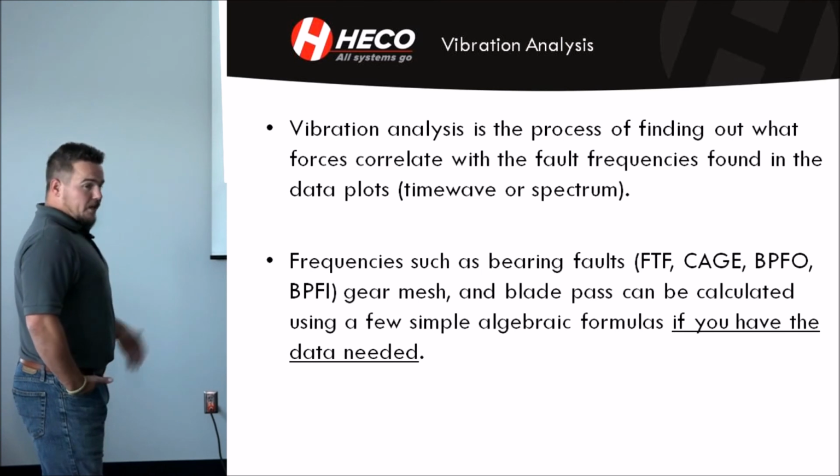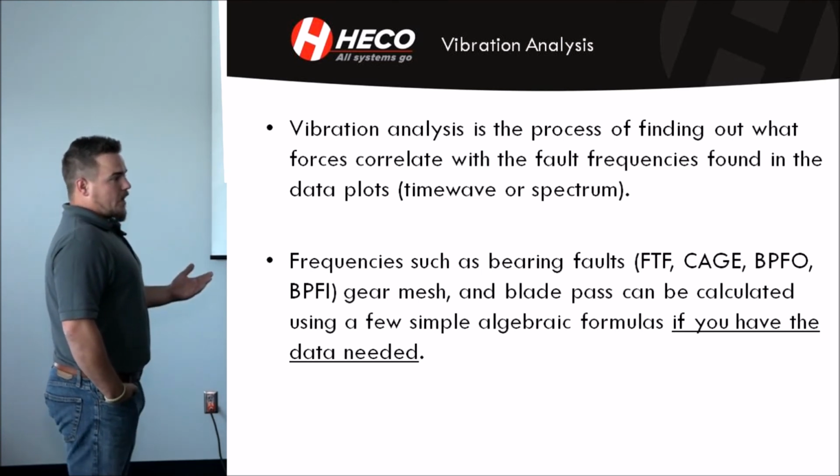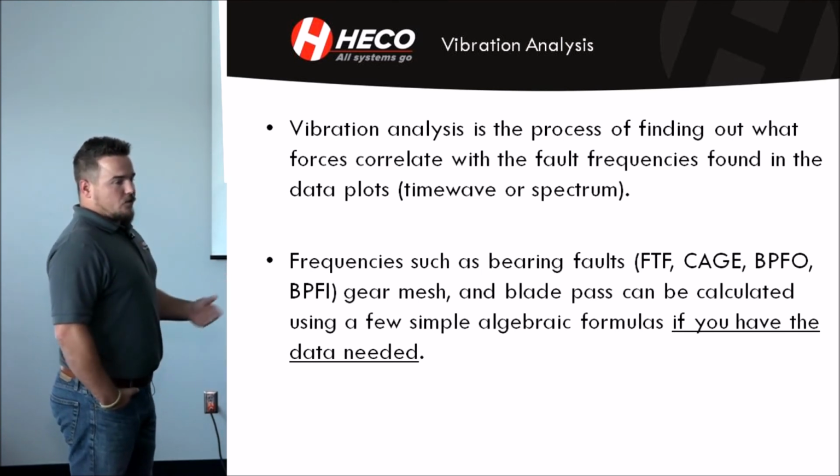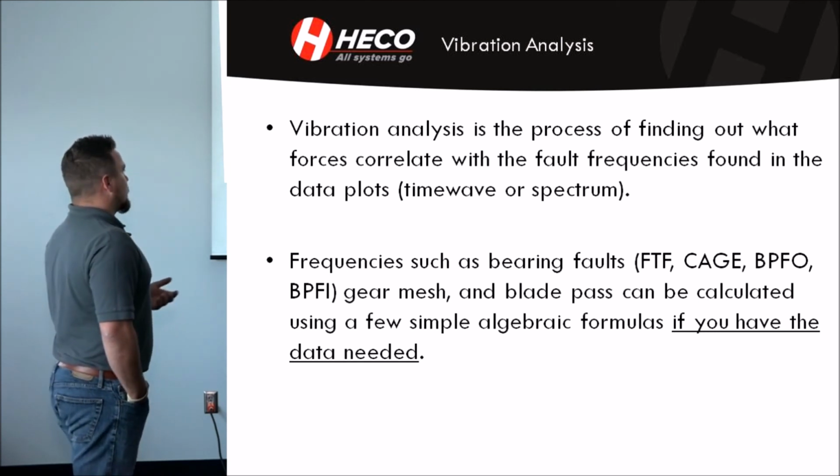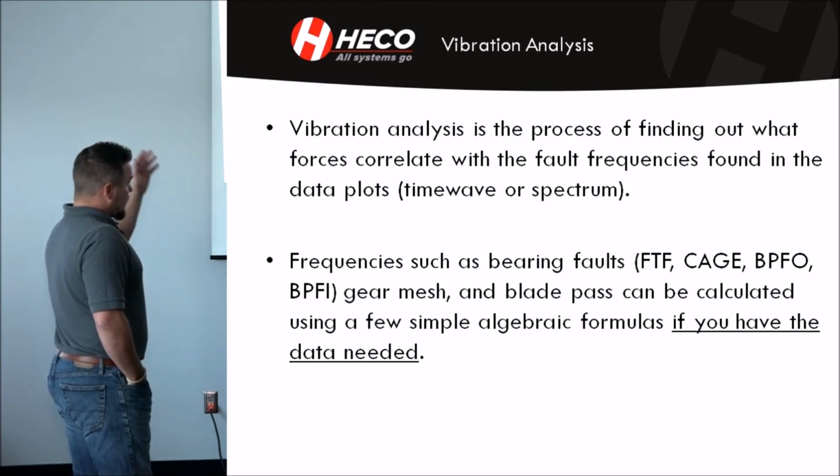Blade pass, you need to know how many blades are in there. If you're seeing a high 9 times on a fan and you don't know if there's 9 blades on there or not, you can't really determine if that's a blade pass issue.